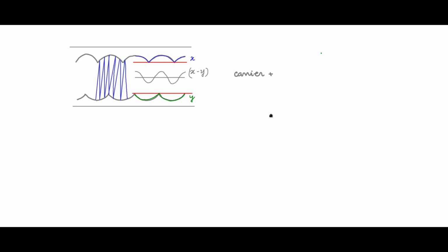Normally half of that value is added to emulate the space vector PWM, and this would be the triplen injection. Then you will get exactly the same type of modulation as what we discussed in the discrete case.